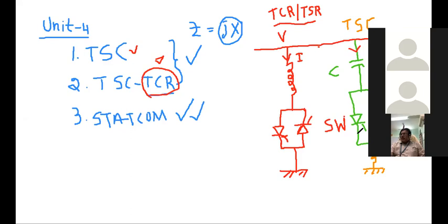Whenever a malfunction, or switching at unwanted time, gives rise to transients, which are injected into the power system, the power system may be damaged because of this. So not only the capacitance and this switch, the power system is also damaged because of these transients. So to limit any transient currents produced due to malfunction of this switching, we use the inductor.